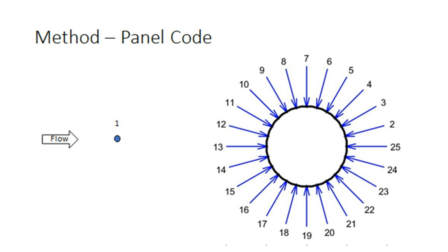Each panel has an associated pressure that points normal and inward to the panel's surface. This value is used to calculate the coefficient of pressure. Using the coefficient of pressure, drag on that panel can then be calculated. It is important to only consider pressure in the direction of flow as per the definition of drag. This means the angle at which the panel lies in the free stream must be taken into account.